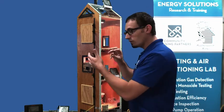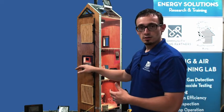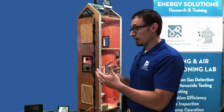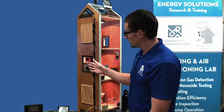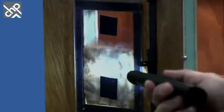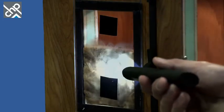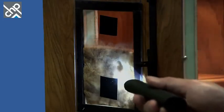But it's moving through this fiberglass insulation, and then it's touching a vapor barrier. So it's condensing on that outside surface. It can't go any farther. So under this condition, this house is just going to keep pumping moisture, pumping moisture, pumping moisture. It's going to keep moving through that fiberglass, and it's going to condense on that surface. So it's not happening up above it. You can see that. Up here in the top half, that's not happening. It's only happening down here. Yeah, see that? Really getting some condensation now.